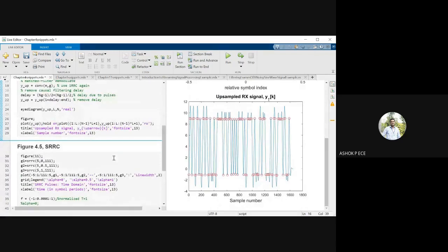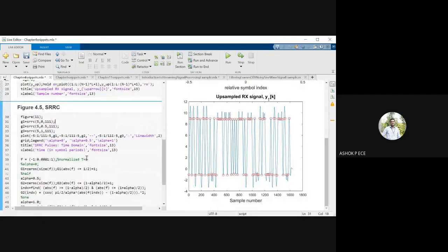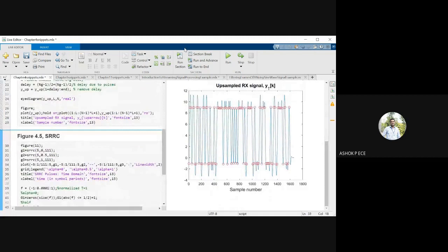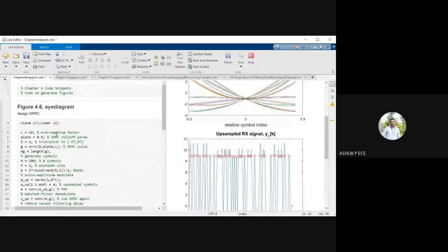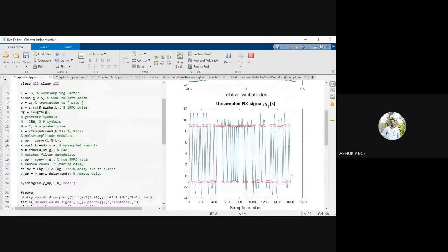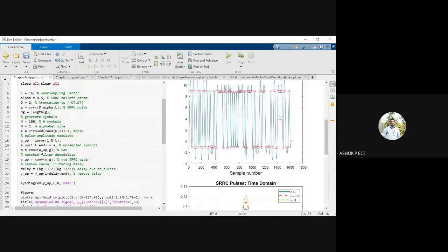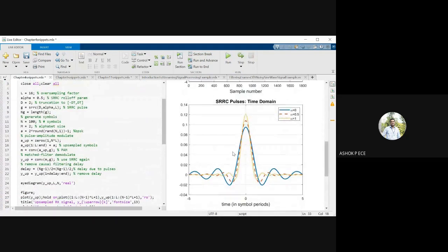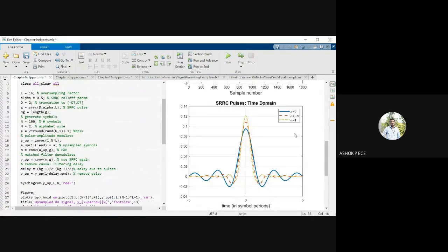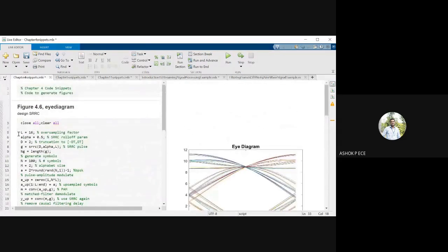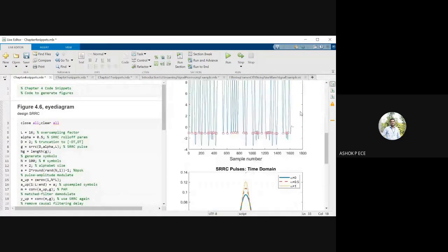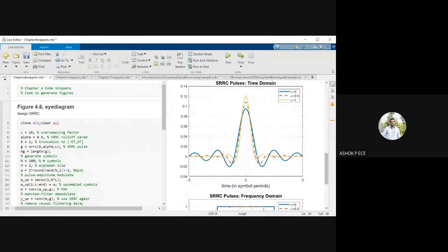Signal we have plotted. And I told you the different carrier signals we are going to use, right? The different signals are going to be called raised cosine pulses. These are the different raised cosine pulses for the different amplitudes. Here we have taken alpha as 0.5. And what does 0.5 mean? It will say how much the signal has to be sharply falling off.